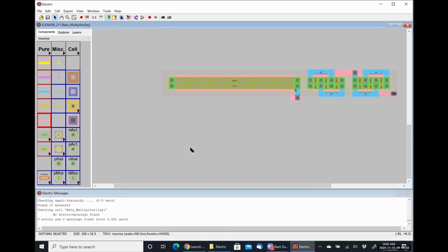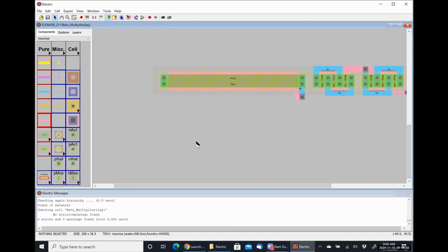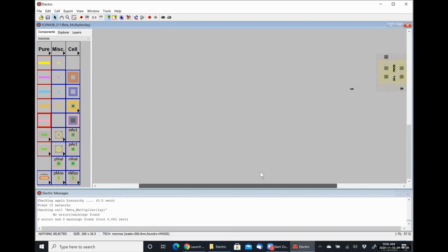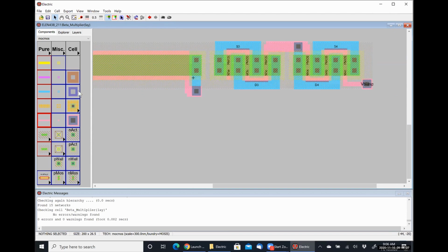So that is the gate drain connection, and I'm going to again have to jump that over my guard ring to get to my NMOS transistors. So I might as well go ahead and put in all of my metal 2 to metal 1 connections. Just stack these guys up. So there's one there.